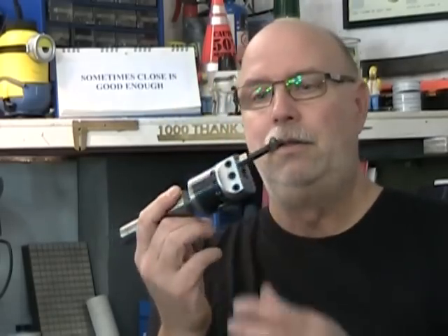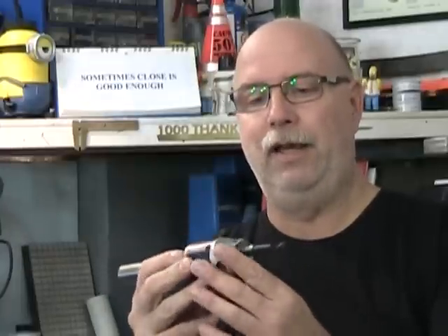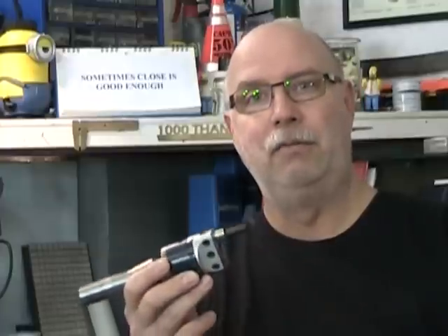So what do we have in our arsenal for positioning? Well, we have boring heads and we have boring bars. So here's an example of a boring head that we could use in a mill that we'll get around to looking at eventually in a video lesson on milling machines. We have a boring head in which is mounted a single lip cutter. And that single lip cutter will follow the axis of the machine and not the pre-drilled hole that it's enlarging, because it's a single lip cutter. It can't follow the hole. It has to be forced to follow the axis.